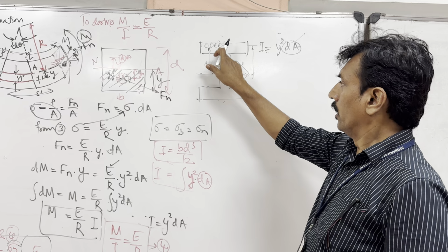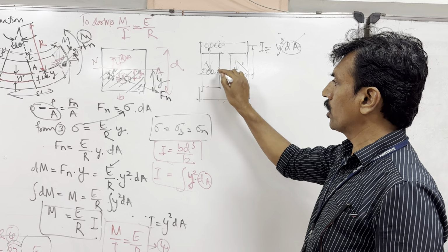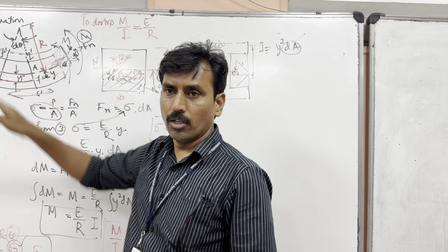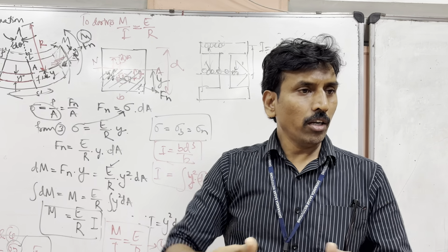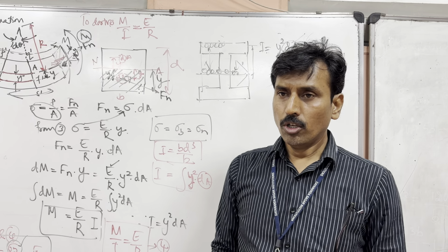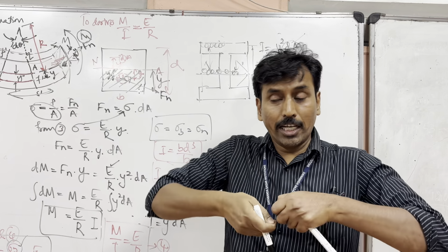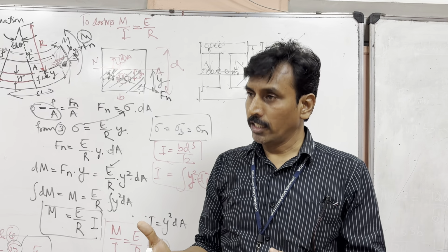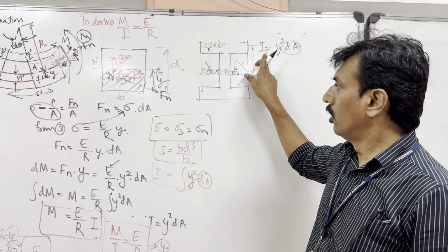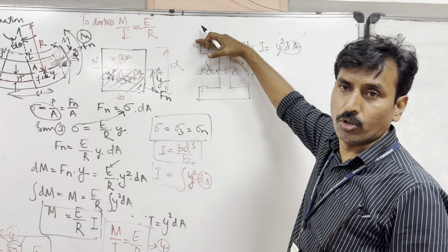So therefore, that is the reason why they don't choose a rectangular section. If you choose a rectangular section, all this material which is very close to the neutral axis doesn't take any bending stress, because you saw that at the neutral axis, they neither get expanded nor compressed. It is simply staying as waste, dead material. So it is not useful. You want the fibers either at the top or at the bottom, which will expand more or contract more. They will participate in taking loads. Therefore, for any beam to have more moment of inertia, more and more material has to be away from the neutral axis.